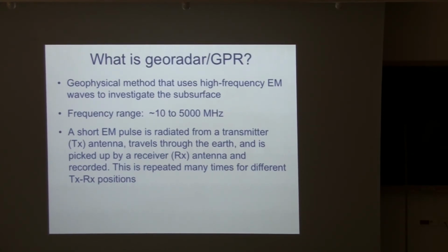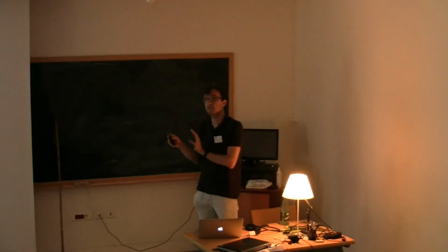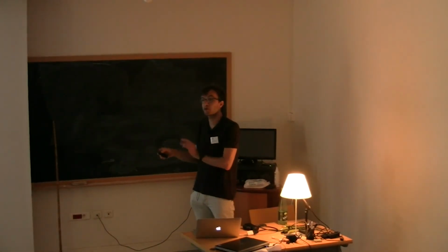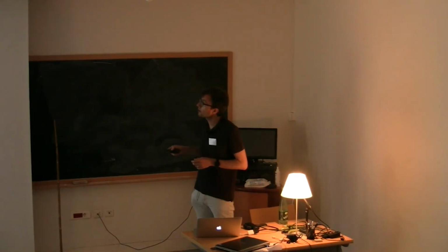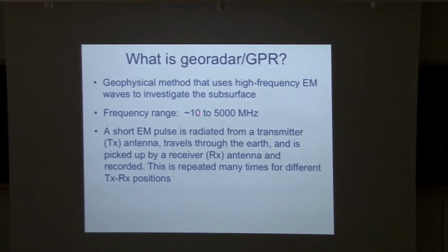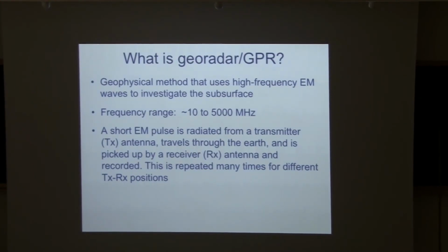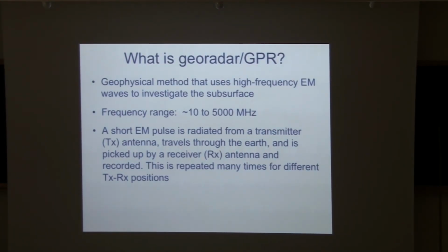So GPR is a bit of a hybrid in some ways between seismics and EM methods. Of course, it's the EM governing equation, same equation as before. It's just that displacement currents now are more important than the diffusive currents. You work in very high frequencies. So here it is acting as a wave. So there's some analogy here to seismics.